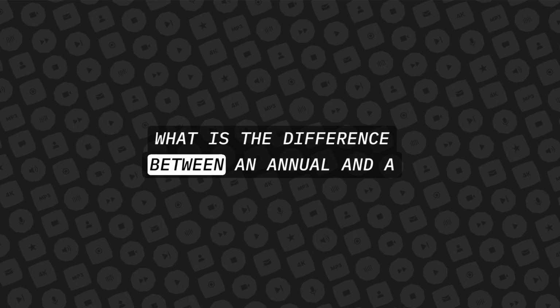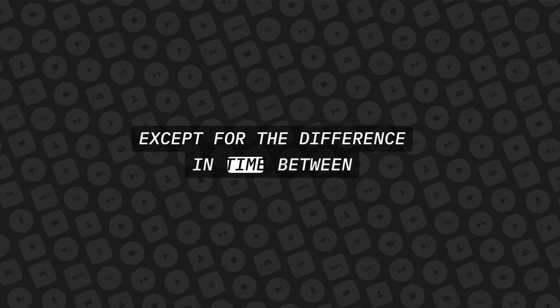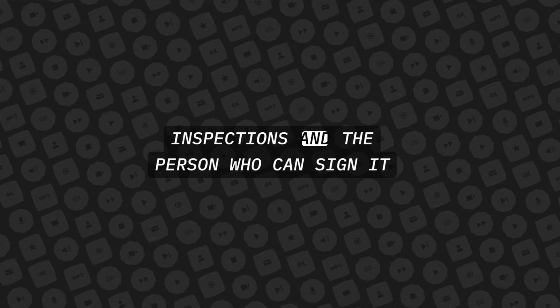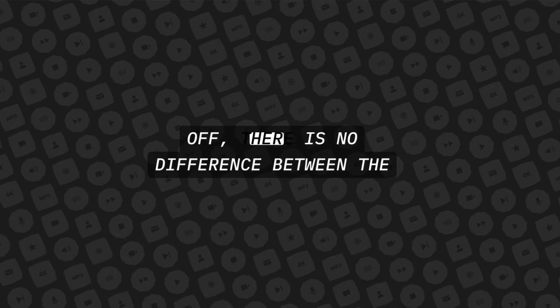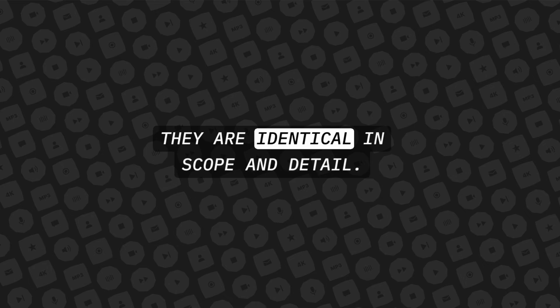What is the difference between an annual and a 100-hour inspection? Except for the difference in time between inspections and the person who can sign it off, there's no difference between the annual and the 100-hour inspection. They're identical in scope and detail.